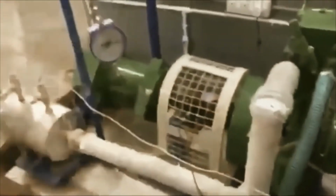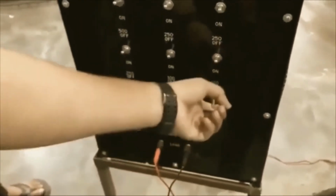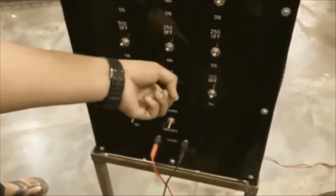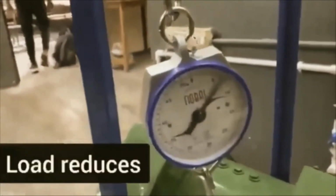For the Williams line method, we applied 2 kilowatt, 3 kilowatt and 4 kilowatt loads and measured the fuel consumption. Here we have taken all the readings for the heat balancing and the Williams line method. At the end, we remove all the load and stop the engine.